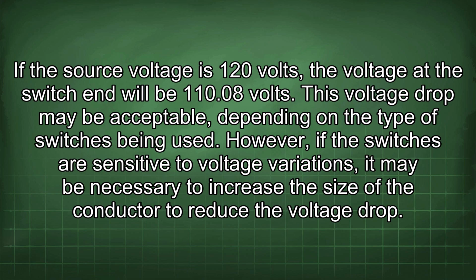This voltage drop may be acceptable, depending on the type of switches being used. However, if the switches are sensitive to voltage variations, it may be necessary to increase the size of the conductor to reduce the voltage drop.